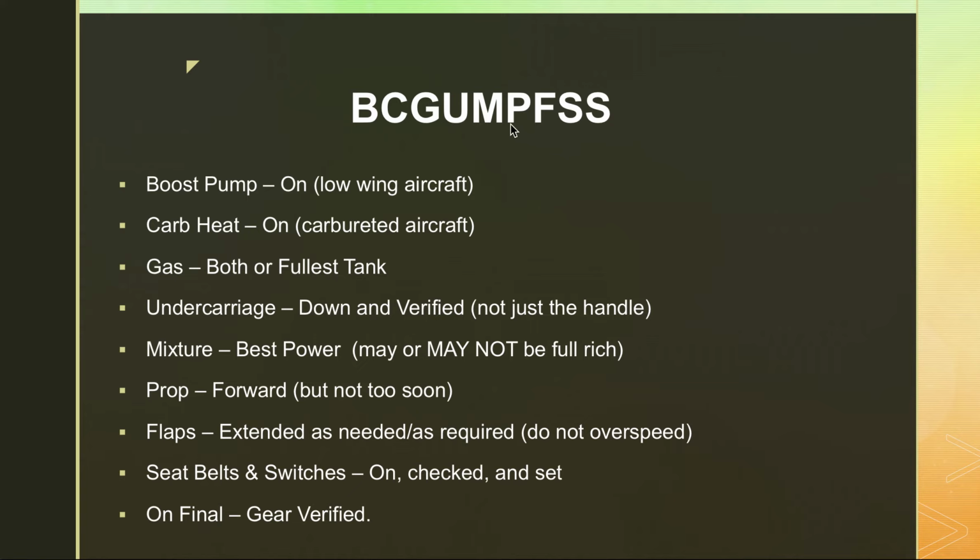Your prop needs to be full forward, but not too soon. Okay, I'm not talking like you're at 10,000 feet. Let's talk about landing, folks. You don't slam the prop full forward. You've used your prop control to reduce your RPM for better cruise performance and make a whole lot less noise. Don't undo that too soon. Generally, I won't go full forward on the prop, I'll be honest with you, until I'm base or final, because anything earlier than that, the prop's going to surge to a high RPM and make a ton of noise for people. And if you haven't picked up on this, people who live around airports don't like airplane noise. So try to keep it a little bit to a dull roar.